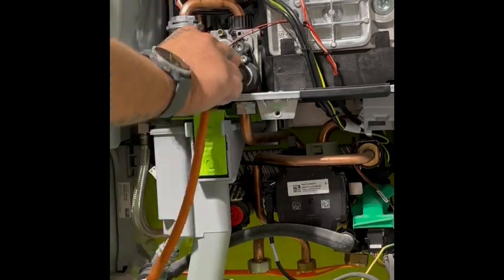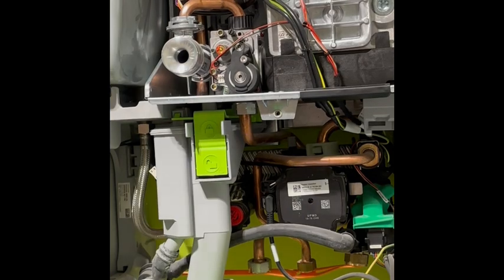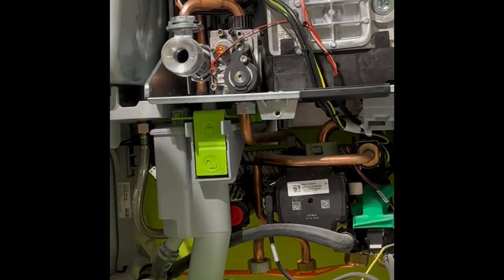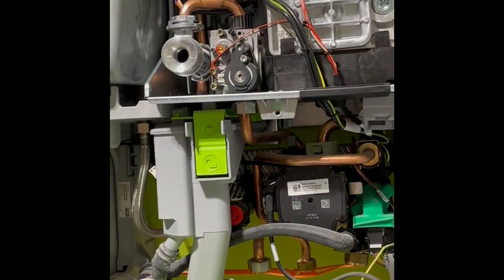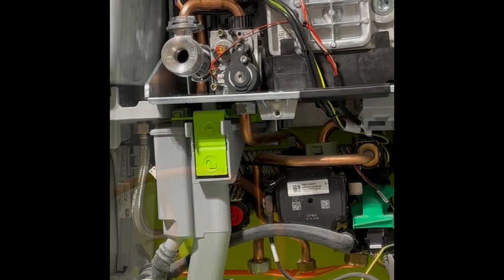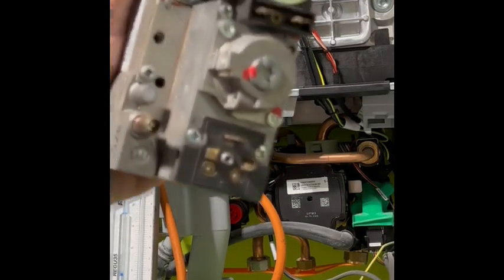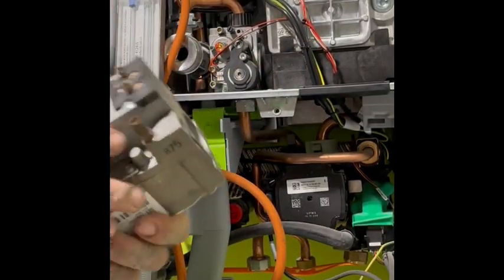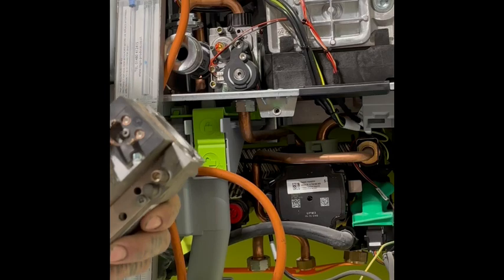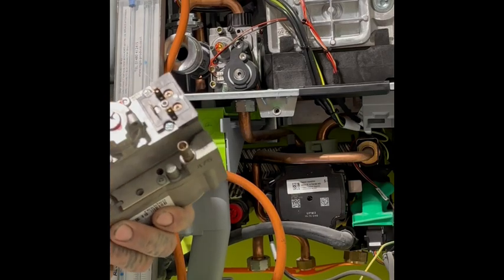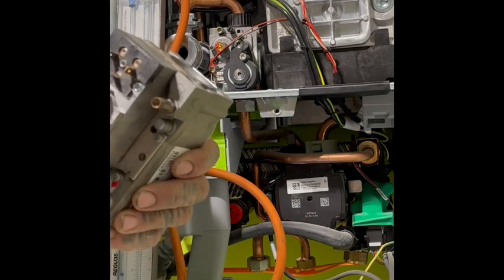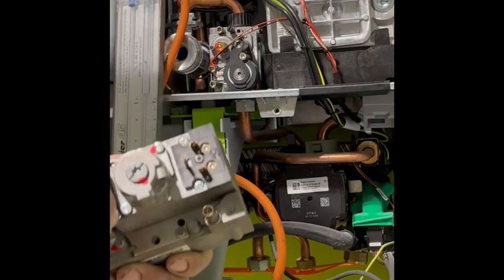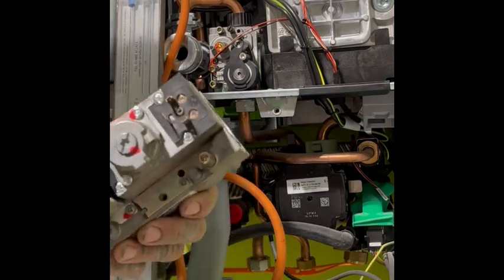Again, with different model boilers and different gas valves, you're able to take a resistance reading across pins on the gas valve. Let me see if I can dig one out and show you. Okay, so this is just a gas valve off another boiler. It's just easy to show this example. So certain boilers, the pins are more available to get readings from, so you can take resistance readings across those. Those resistance readings will be listed in the manufacturer's instructions.